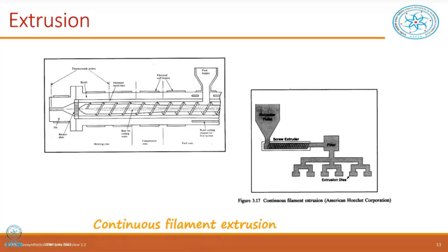And by and large, because most of these geosynthetics we are going to talk of will be exposed at least for some time during construction, adding 2% carbon black is becoming a very common feature now. This and any other additives required for its performance in the field are already added and mixed during various conditions. Then that mixture is brought here in small granular form. So these granules are placed in the hopper, and then of course the continuous process begins.